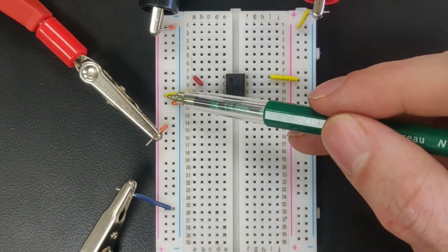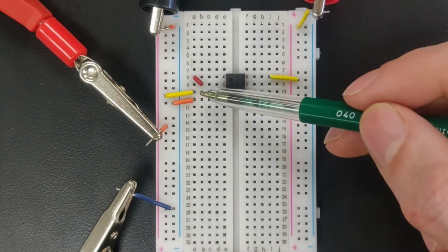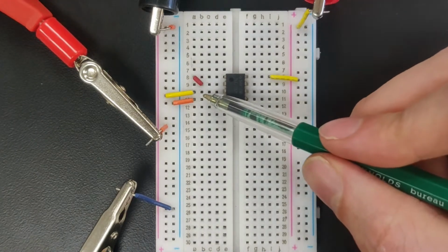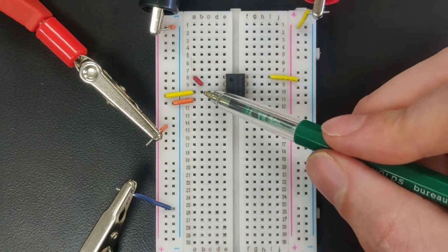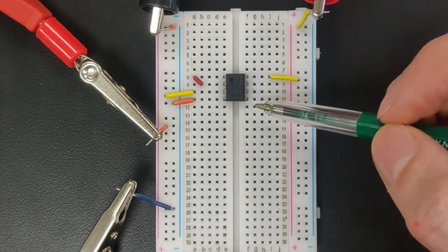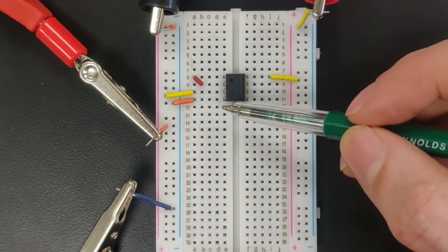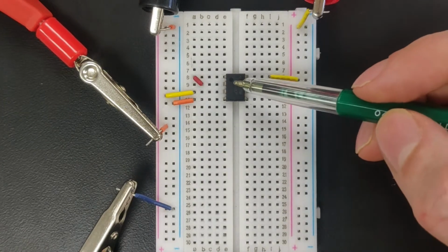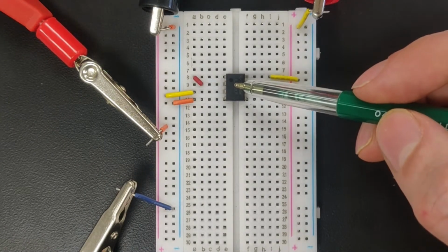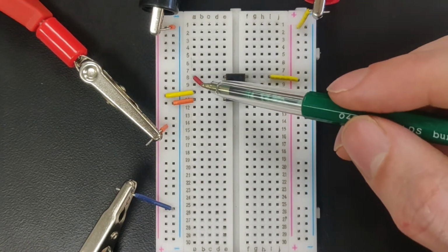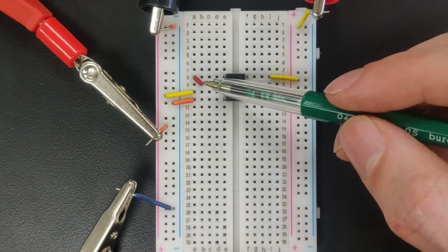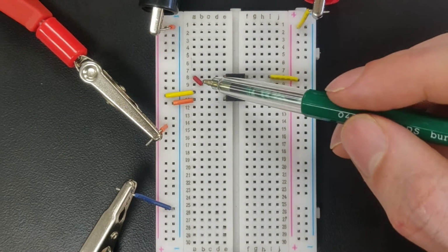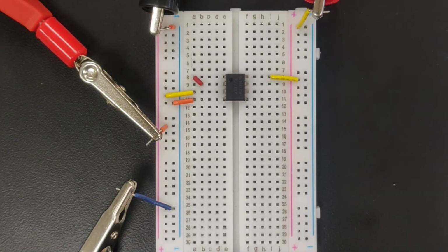You can see here where it's linked over to our positive Vin pin, where it will eventually go through the op amp and then be output. And our negative Vin and our Vout are linked together, and you can see that with this red wire right here combining these two rows. Okay, that's the circuit. Let's go to the analysis.